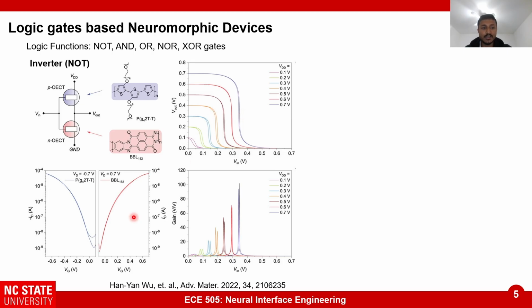Now, you might have noticed that the transfer characteristics here are almost the same as a typical transistor, but if you are more careful, you can notice that the voltage windows are extremely low. There are two reasons for it. First of all, since we're using polymers and there's a doping, by driving the voltage at the gate electrode, we can dope the polymer very easily because of its oxidation state. And secondly, the advantage that we have with this is that we're operating well below the stability window of water.